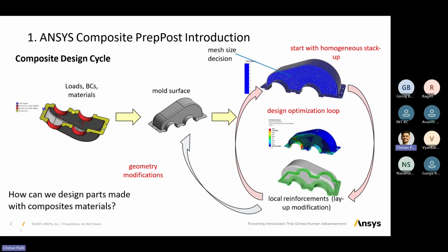you are creating whatever structure that you might be using for the simulation, you should always know how you are going to proceed with the composite modeling over there, whether applying composites on a particular surface where there are a lot of curvatures is possible, or whether we need to divide the particular model into smaller sections so that the composite layup might not get affected, the fiber orientation might not get affected. You need to be much precise with those kind of things as well.